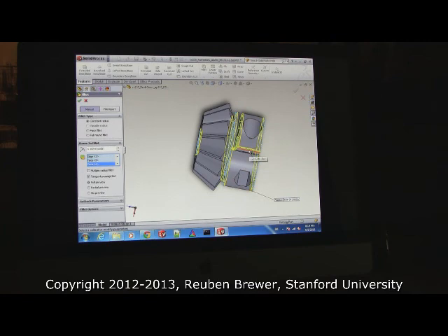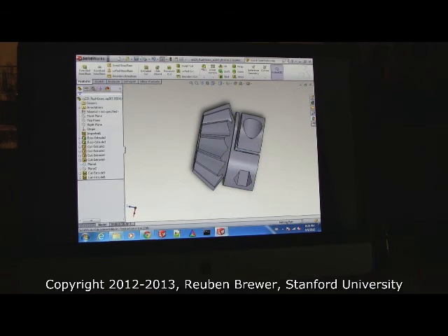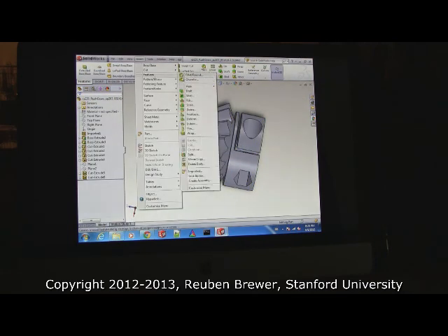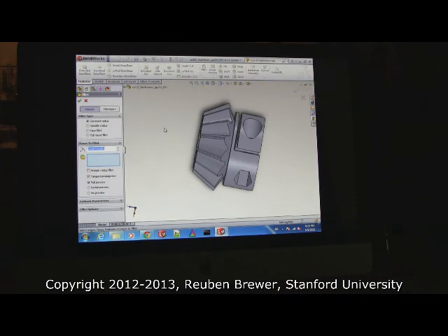Does anyone have fillets at this point? Would anyone like me to show you again how to do fillets? Yes. Okay. Insert, feature, fillet. Everybody there? If you have an external monitor at home that's bigger, you might want to use it because otherwise it's going to be painful. I've got this nice shiny Apple Tosh. Okay, we're good? Now set the fillet radius to 0.5 divided by 25.4.